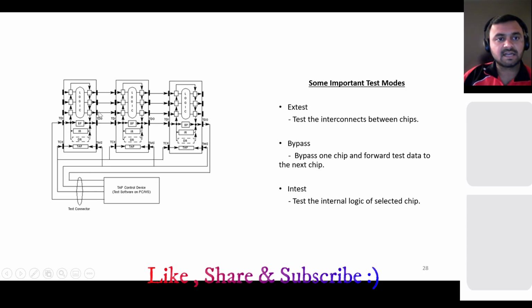And then EXTEST means the connectivity check between these 2 chips. Some of the signals will go from one chip to the other chip, and this connectivity between these 2 chips will be tested by EXTEST. So basically you shift in the data from here, and then you shift out, and again shift in, shift out. So you test the connectivity between these 2 chips. And there is INTEST, which will test the internal logic. It will perform the test on this internal logic. So these are the 3 basic or important test modes for JTAG. There are many other modes, like clamp, highz, there are so many, but just to make it easy, we focus on these 3.